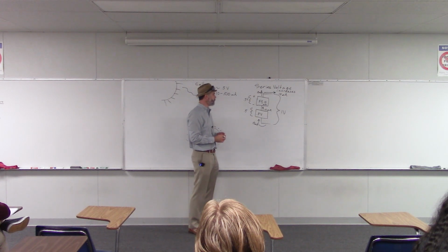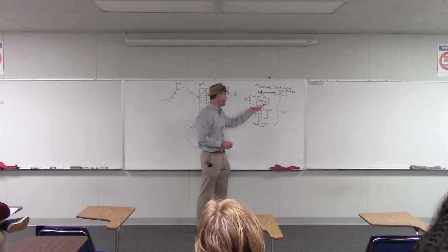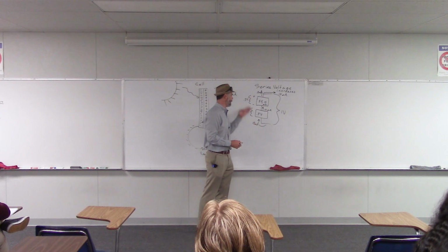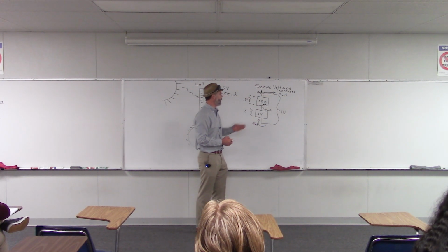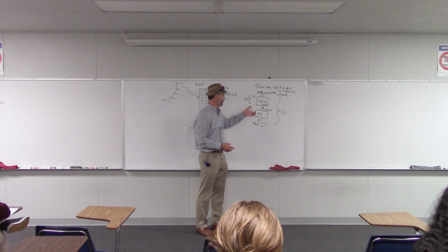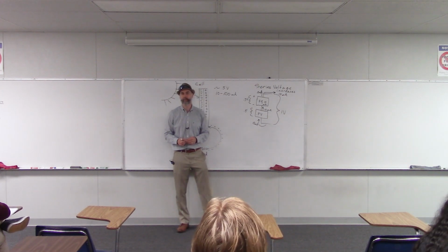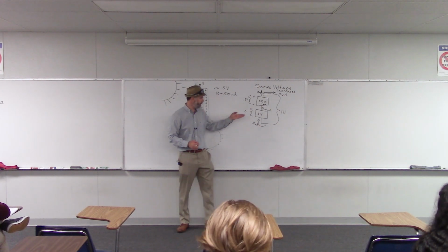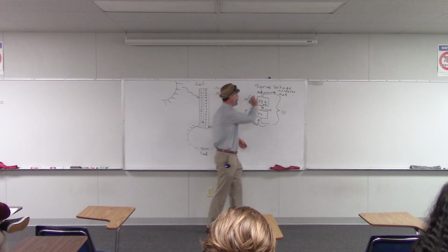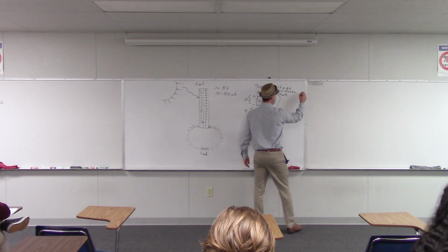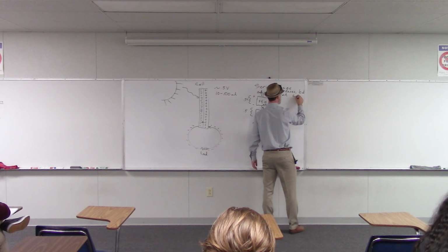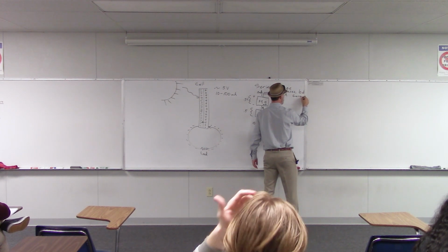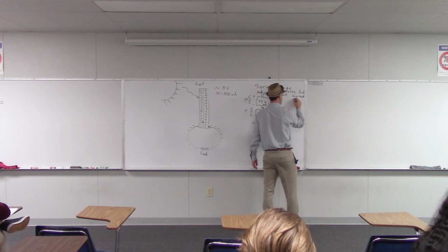So each cell produces 10 milliamps, and the total circuit produces 10 milliamps as well. So are you increasing the current by putting cells in series? No, it stays the same. So in series, the voltage increases, but the current stays the same.